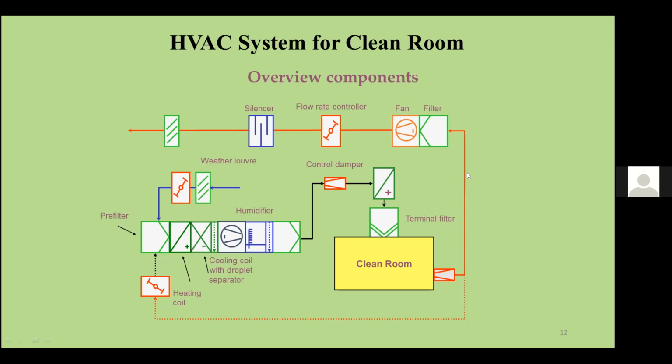They collect the outlet gas, and outside the clean room some bigger chamber is there. I don't think you remember or not, but when you push the door lock button, near that door lock button there is a chamber, a circular thing. This is actually the silencer. This gas is passed through that silencer, which dilutes that gas, and after that dilution the gas is passed to the environment. That diluted gas is not as hazardous as compared to pure gas.